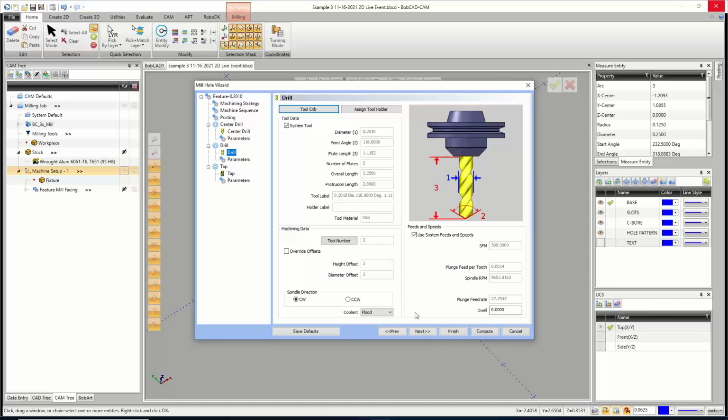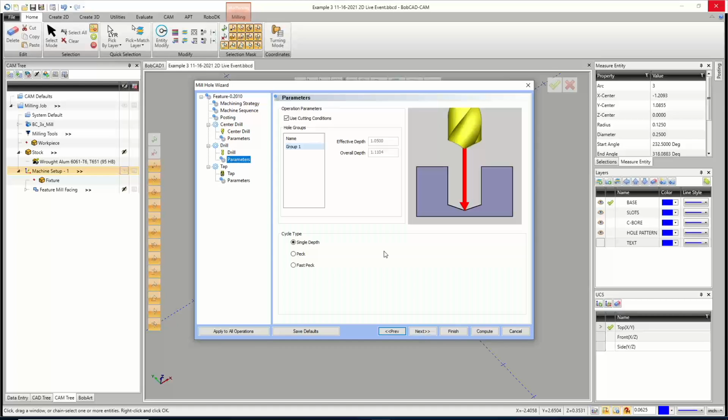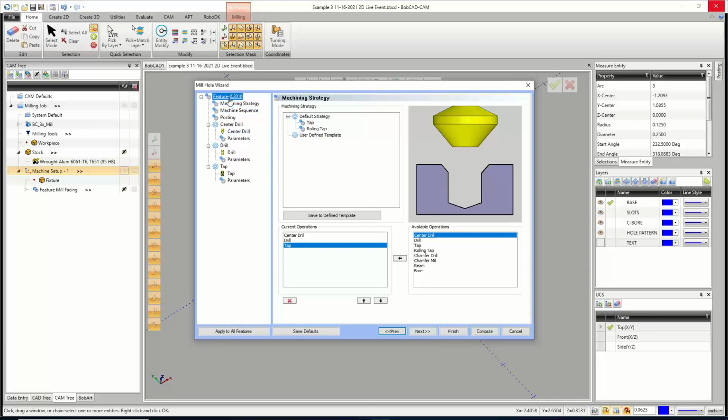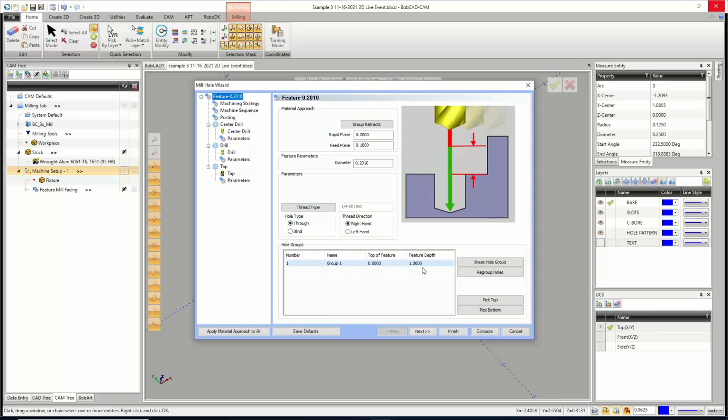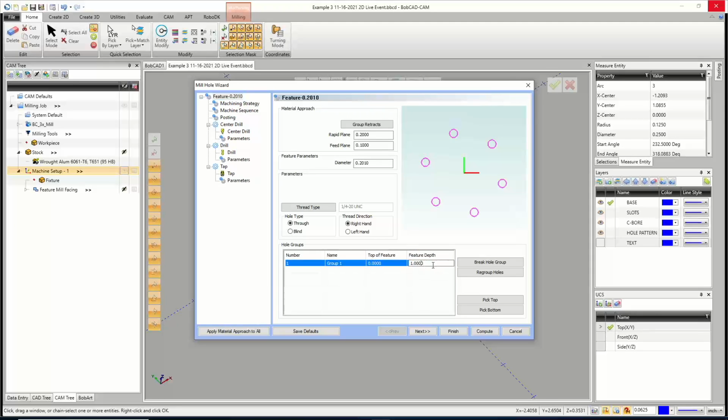So we'll go ahead and hit next right here. And this is the drill. So our effective depth is that 1 inch plus the 50 thou, which as David just pointed out, we need 1.1. So yes, we could go back to the beginning, and this is probably where I'd do it. This is where I'd recommend doing it because it's going to lock it in. We could do it on the other page as well, but let's say we just want to go 1.2.